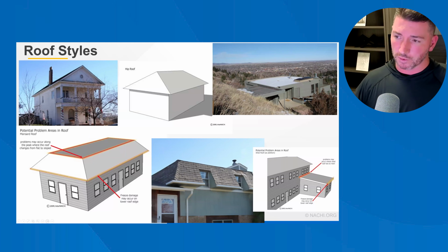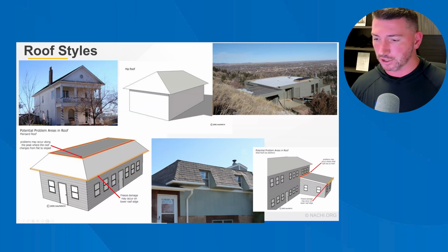When it goes above 21/12, building code states that you need to hand seal all the roof shingles. And as you can imagine, access to the roofing system is very difficult. So flat roofs, or low slope roofs, as I call them, have very little slope. A typical slope would be 1/12. They can be less than that. I think they can't be any less than a quarter inch over 10 feet. Flat roofs may drain over roof edges or through scuppers installed in the parapet wall around the perimeter.